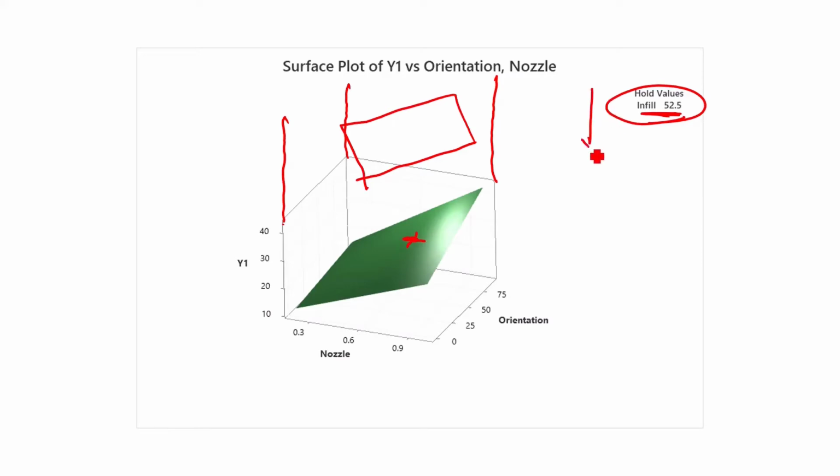Or if I wound the infill in the right direction, this plane would move down the lift shaft. So there might be a higher value, but 50 odd maybe, I don't know where it might go, if you move the infill. But that's why I said the first thing you want to do is just leave the infill at the midpoint, and maybe you can come back and adjust it later if you want to move this plane up and down in the column where it's sitting.